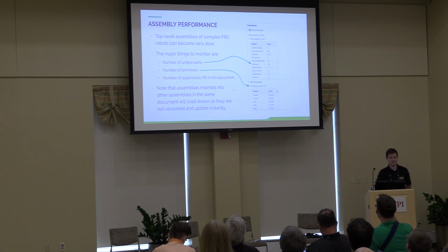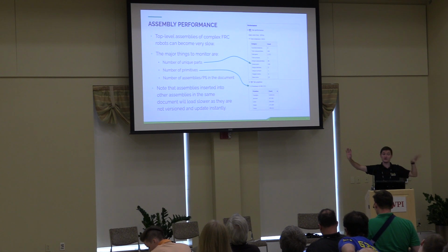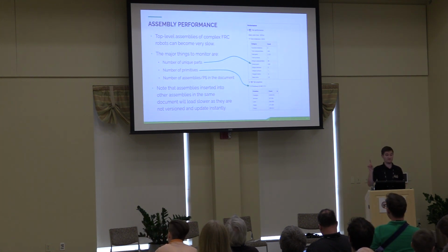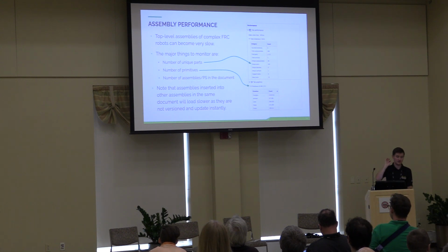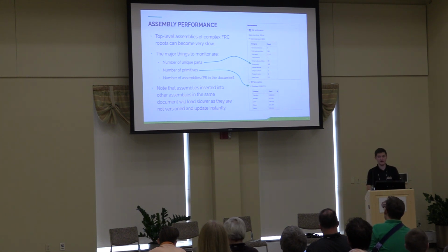Also note that when you make a sub-assembly and insert it into the top level, that does load faster than making everything in one document, because it is loading a version of the assembly, not the live assembly. If you are inserting assemblies into assemblies in one document, when you make a change over here, it doesn't instantly show up over here. You don't have to do versions. Versions do load faster, so a little bit hand-wavy there, but that's another advantage of the multi-document structure.